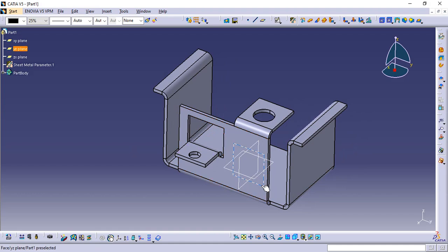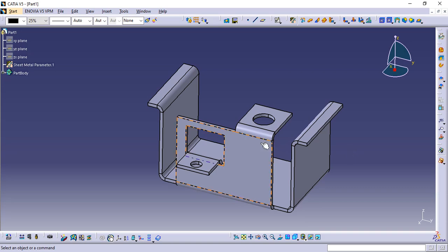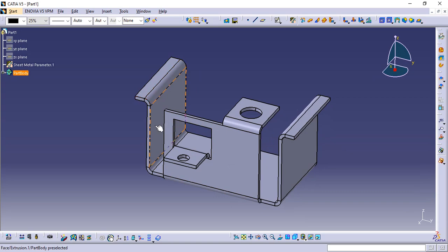From the starting itself, I forgot to reveal an important thing that you need to keep in your mind while designing a sheet metal part. It is CAD modeling, so we directly design this component with these bends. But in the manufacturing process, they take a plain sheet, and from the plain sheet they will cut the portions they want based on the dimensions, and from that cut piece they will bend these walls. That is how sheet metal parts are manufactured.